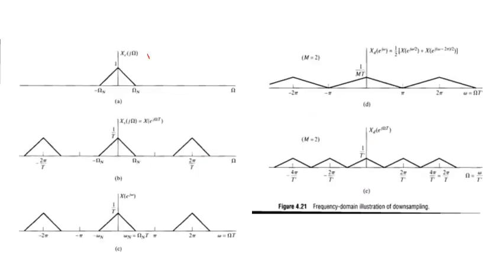This is our continuous-time signal spectrum with a maximum amplitude of 1. Omega_N is the Nyquist frequency, that is, the maximum frequency. This signal is band limited. Now this is the sampled version that we get after convolving this signal with a periodic impulse train, and the scaling of this becomes 1/T. So we have a copy at 0. This is omega_s, this is minus omega_s, and the heights of all these are 1/T.